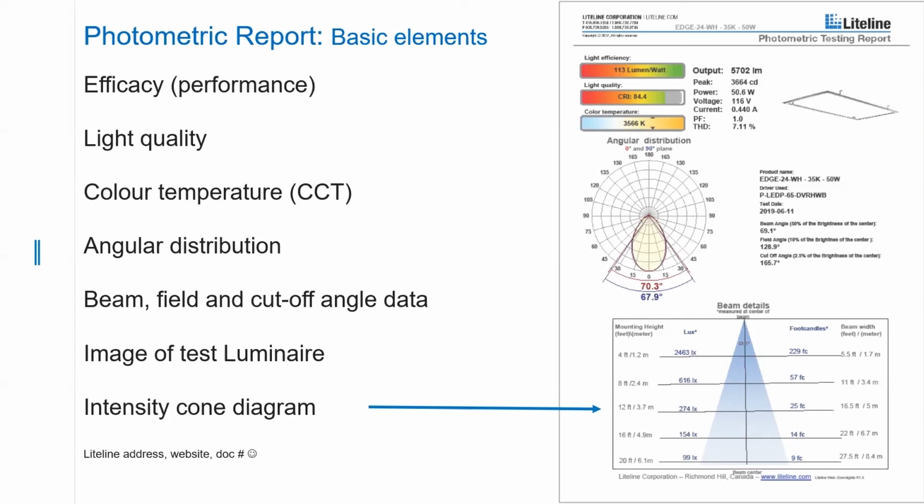So depending on your height, your pool of light, you either want 50% of it overlapping for absolute uniformity, or you may want drama, you may want contrast. So we want pools of light, and then we want our recessed lights maybe centered on 7 or 8 foot centers, so that we have these very distinct pools of light that provide contrast.